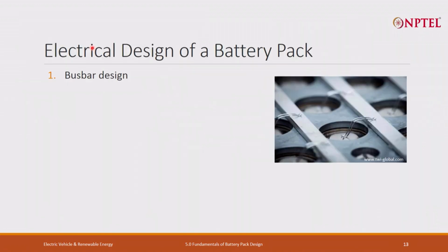So, what are the things required for the electrical design of the battery pack? The first one is bus bar design. When I say bus bar design, what are the important aspects? It is conductor material selection. You always try to select a conductor which has the least resistance to the current flow, or whose resistivity is minimum. Other things also come into the picture, like mechanical strength,